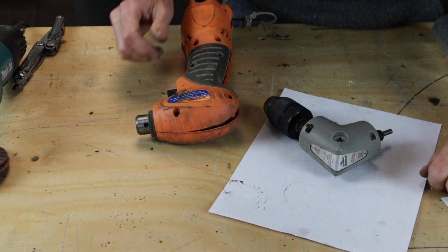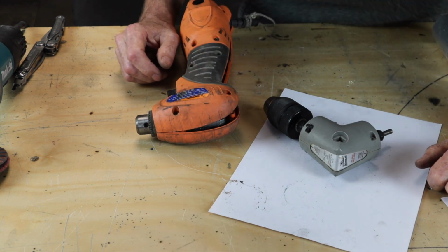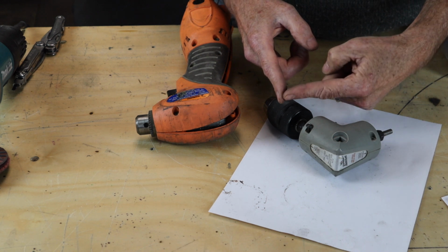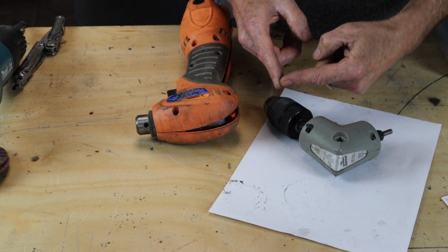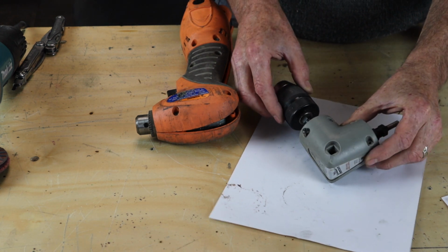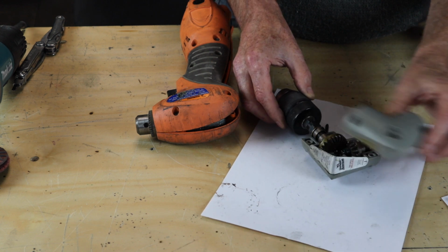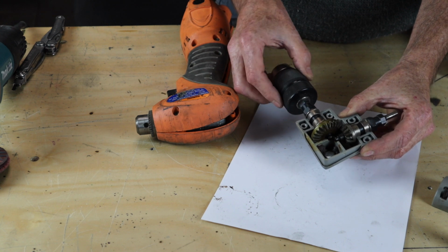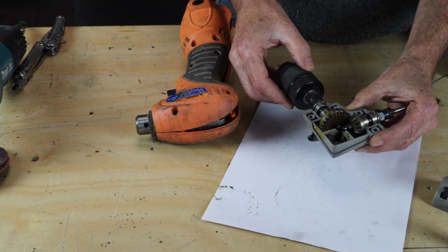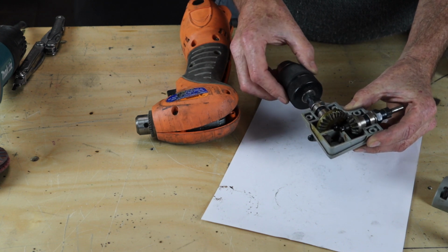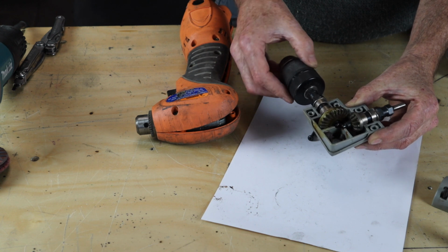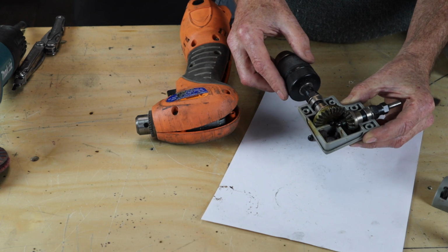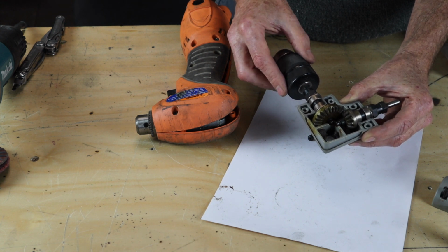Let's move on. So if you would like to change the direction of your motion from this way to that way, you're probably going to need some bevel gears. This is a right-angled drill attachment, and if we remove the case, we can see it has a set of beveled gears, and one of them is bigger than the other. One of them has exactly twice the number of teeth of the other, so you can swap which side the chuck goes on, so you can have either twice the speed or twice the force.